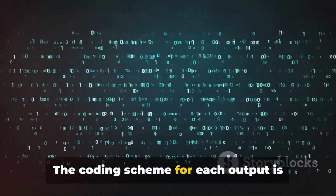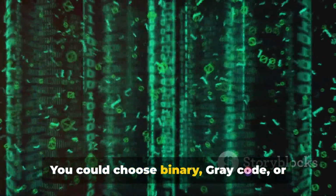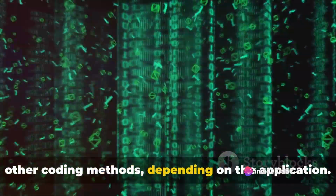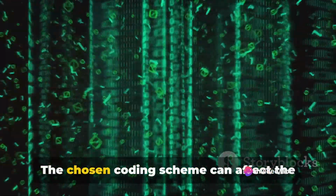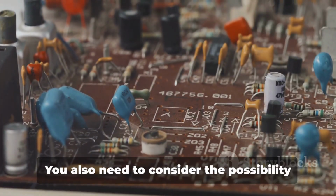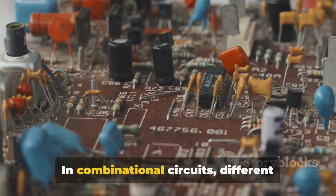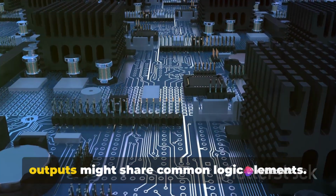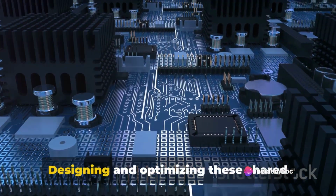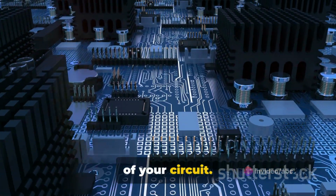The coding scheme for each output is another important design consideration. You could choose binary, gray code, or other coding methods depending on the application. The chosen coding scheme can affect the complexity and efficiency of your circuit. You also need to consider the possibility of shared logic elements. In combinational circuits, different outputs might share common logic elements. Designing and optimizing these shared elements can help improve the efficiency of your circuit.